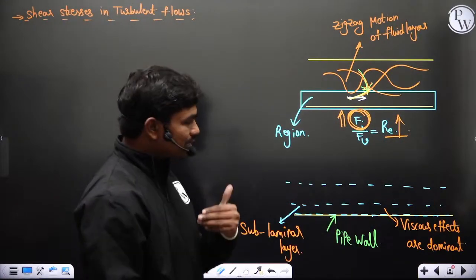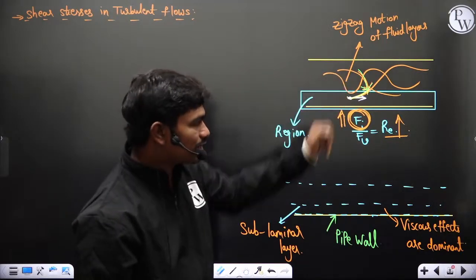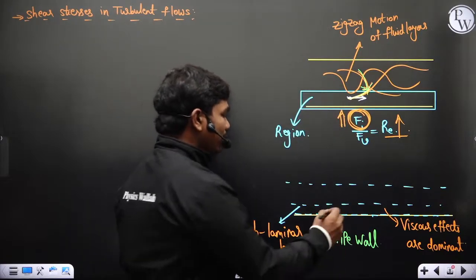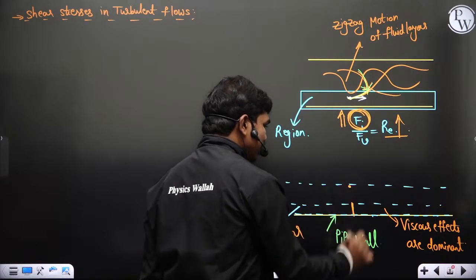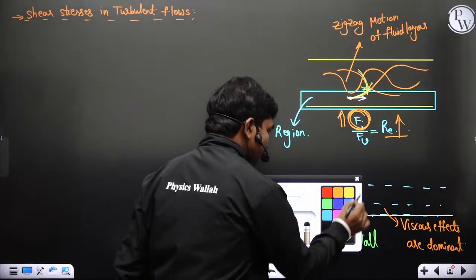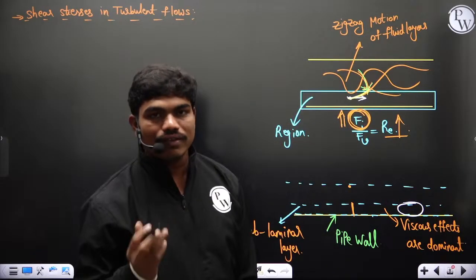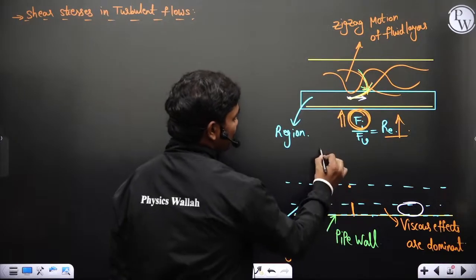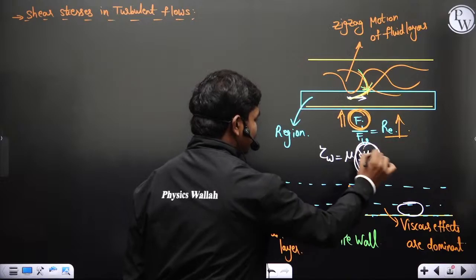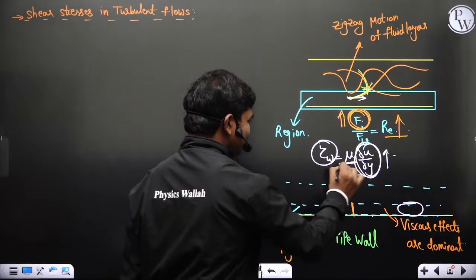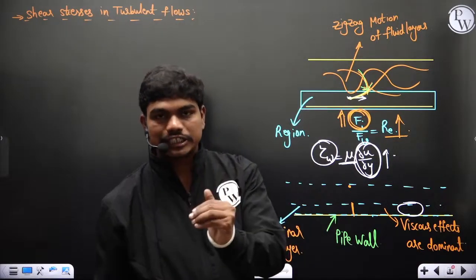So when Reynolds number of the flow is very high, even though there is presence of the viscous plate, the fluid particles will try to move effectively, and inertia forces are very high. So what happens, within a very small gap, the particles keep attaining the velocities, and within this region velocity gradients are very large. So when velocity gradients are very large, if this is a Newtonian fluid, for example, tau W is equal to mu into dou U by dou Y. Now when these velocity gradients are very large, the shear due to this viscosity is actually large. So that's why in a region which is very close to the plate, viscous shears are pretty much dominant.